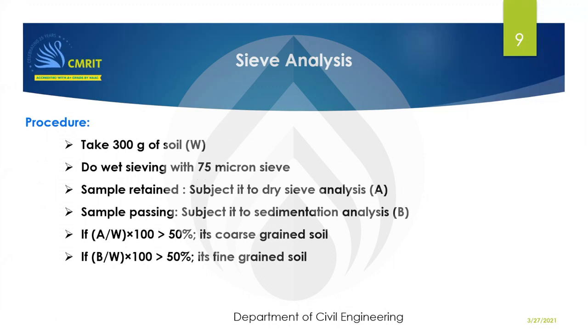What do you mean by a sieve? A sieve is something like a cloth, but when we have larger sizes, it will be made up of wire mesh itself. Generally a 75 micron sieve will be more like a cloth. We take a sample and do the wet sieving. I will try to show one video on wet sieving towards the end, based upon the time, so that people will get a feel for how to do that.